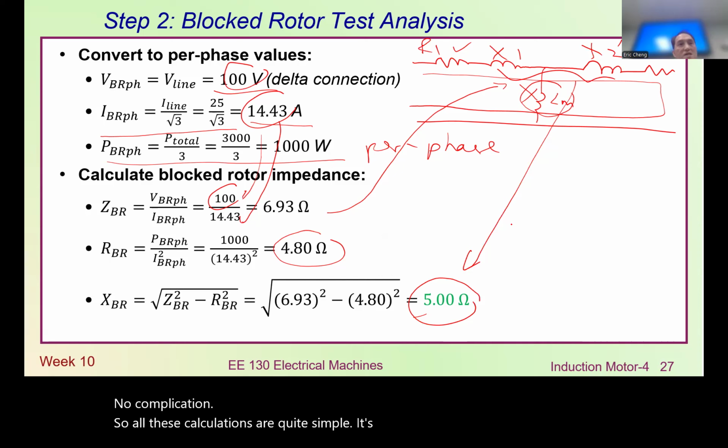You see, 75 degrees C approaches the limitation for the motor. Anybody can tell me what's the limitation for motor temperature? Maybe the insulation of the windings. Exactly. If you go to any website and search for the temperature withstanding of the copper wire enamel, the coating called enamel, they usually can only go up to 120 degrees C. For really good, expensive copper winding, it can go up to 180. So most of the motors you're using today are probably only 120. So 75 is still under the limit, but if you keep energizing the motor at a high temperature approaching 100, it goes toward that limit.